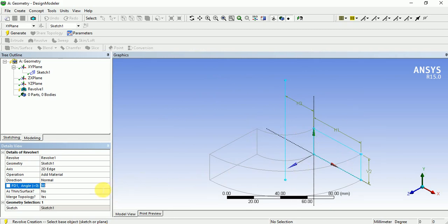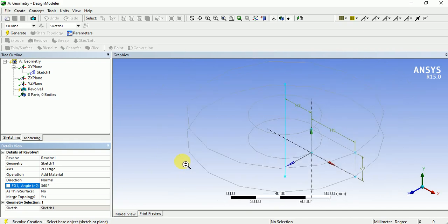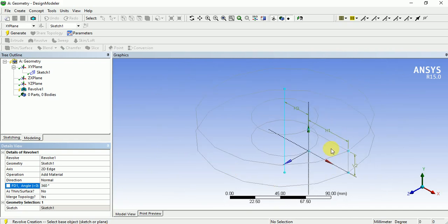So based upon this, we will choose the degrees for the material. These options help to change the degrees about the revolve. And here we have one more option. This is add frozen and add material. Add material is the normal one. So finally the first step was completed.